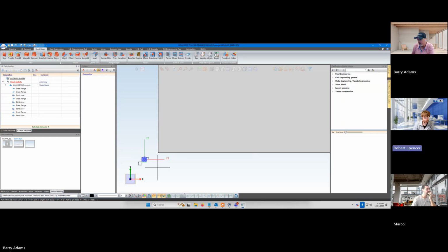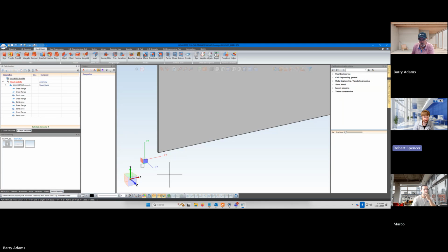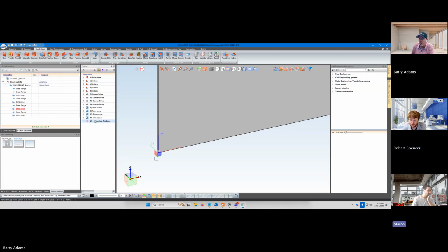Now, before we run the command to reestablish that origin, I would roll all my flanges back up so that you only have the base sheet in the feature step, so that we got that nice sharp corner that we can select. So just pull this up here. Yep. That point. And then, wish I could just drag and drop.